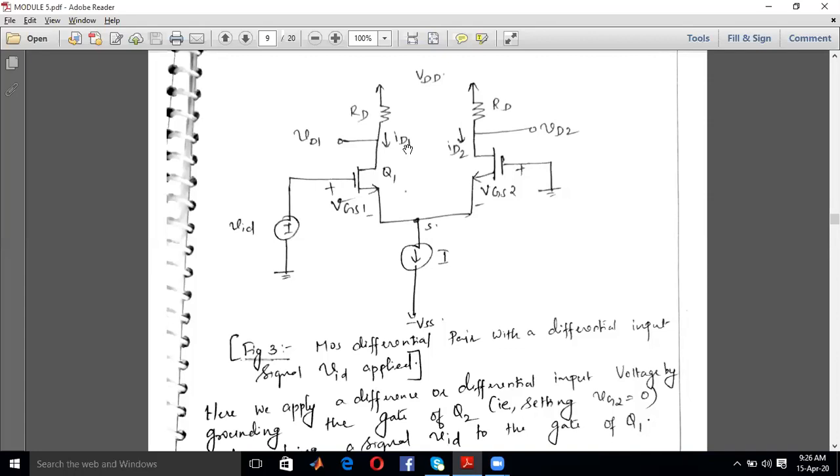If the output is not equal to 0, then you can say that your differential amplifier is operating in differential mode of operation. It is not rejecting the signal. If it was rejecting the signal, it would obviously not be working; it would have the common mode rejection property which we learned in the previous operation. But this mode of operation deals with the two transistors where the currents are different. Since the currents are different, the two output terminal voltages will be different. So the differential output will be a non-zero value, having a positive or a negative value.